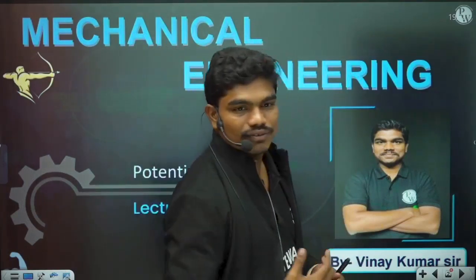I told you, this is some extra part of the syllabus which I am teaching you. This potential flow is basically the ideal flow, in other words. We have defined potential flows as the flows which are incompressible, of course, and irrotational and also inviscid, correct? I have given you some quick points of this potential flow in the previous lecture, like how to write the complex potential function, all these things. This is the continuation of the basic flows that we have seen.